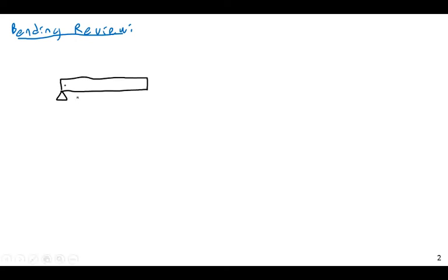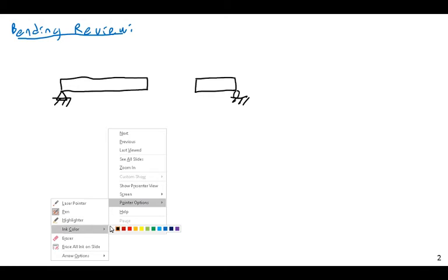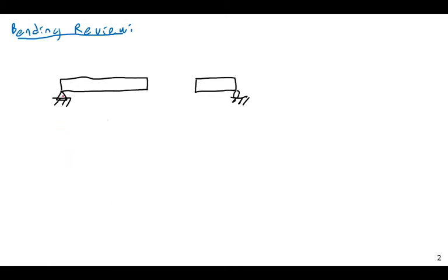Method of sections, we have a beam with a cut, and there is going to be another piece of this over here. So we have cut this beam somewhere along its middle to analyze the internal forces within it, namely the shear and the moment. Now, of course, we can have axial force, but we're very familiar with that from our explorations of axial members, so that should go without saying.